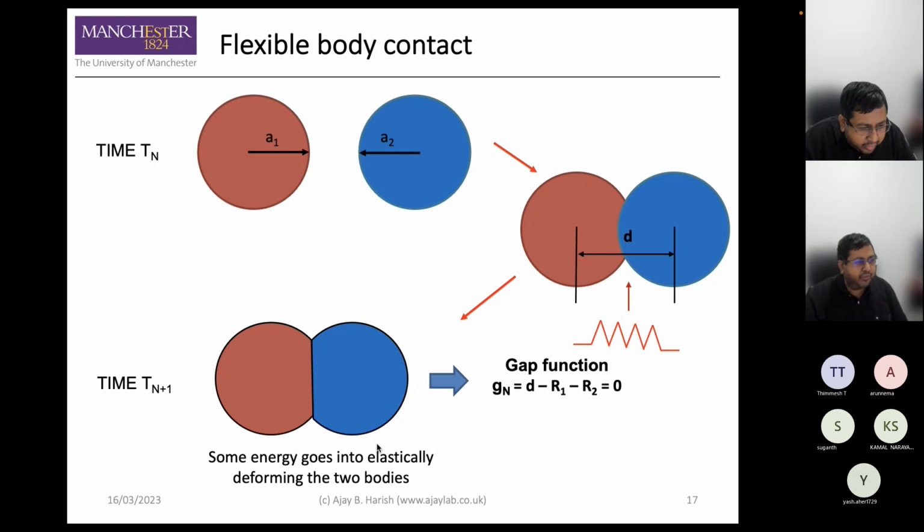A very simple way of thinking about it is if we have two balloons coming into contact with each other. Let's say we can initially assume, in a computational framework, that they're not in contact. It's a nonlinear problem. Solve assuming they're not in contact, check if they're in contact. Then again solve, and check. If they're not in contact, everything is nice. Generally, we'll almost never get a situation where they're exactly in contact.